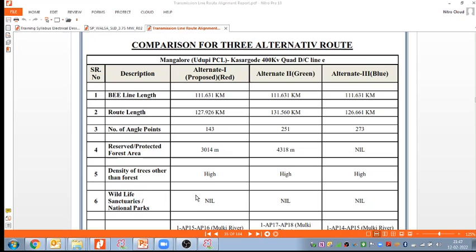About the 1200 kilovolt transmission line test station, Silpa: it is where we apply the 1200 kilovolt on the transmission towers, the equipment, and the transformer, to check whether that equipment withstands 1200 kilovolt or not.